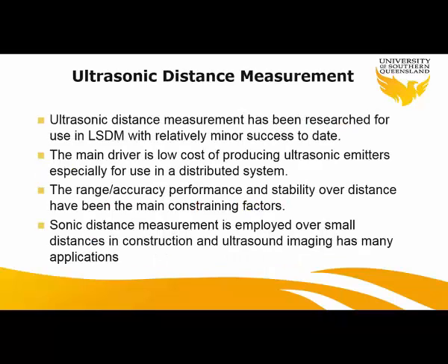The last technique is ultrasonic distance measurement. Ultrasonic distance measurement has been used for a long time, but it's not really an accurate technique to be used, to be honest. So it's a very limited area that you can use, especially for short range distances only. But because of its low cost, some people still prefer to use this rather than the more expensive one if they don't need very precise accuracy.